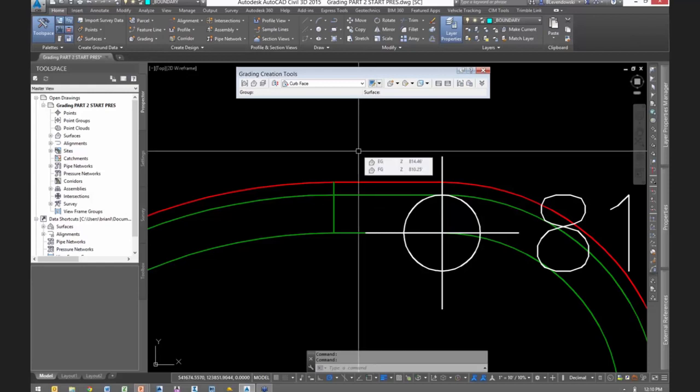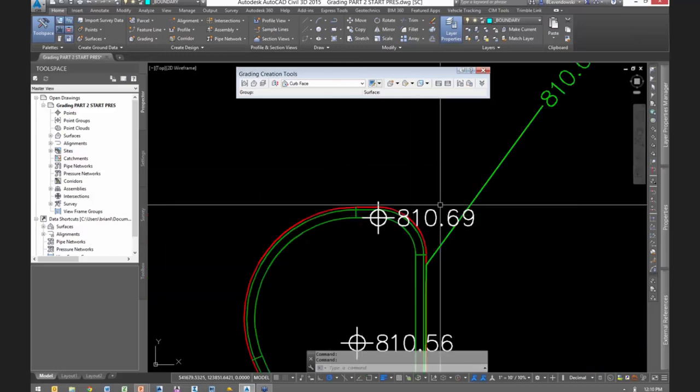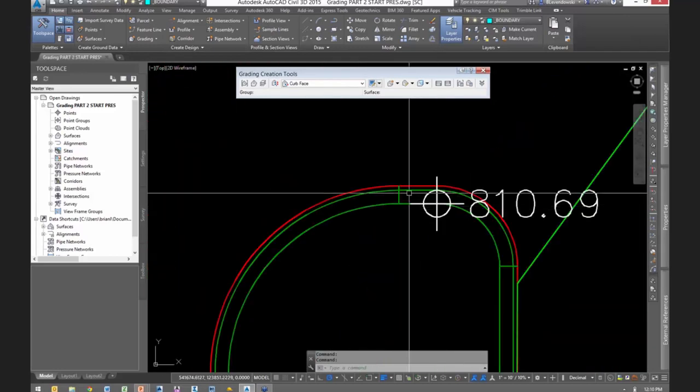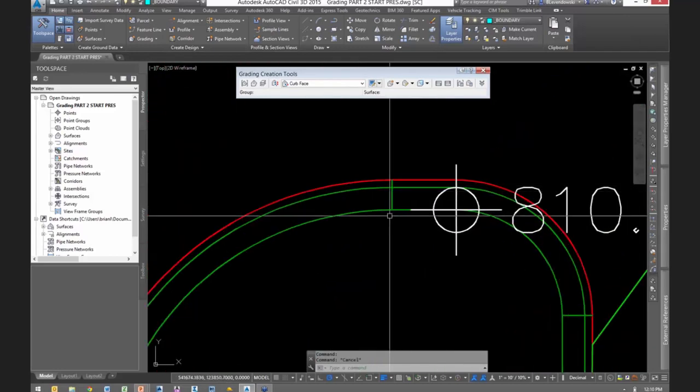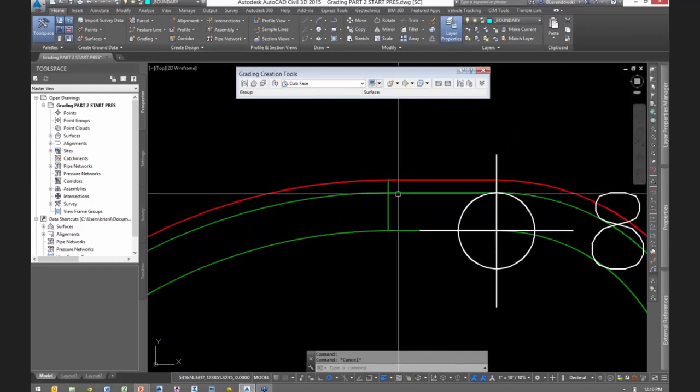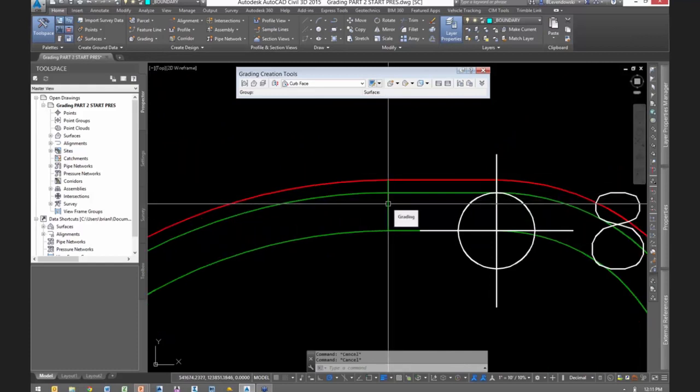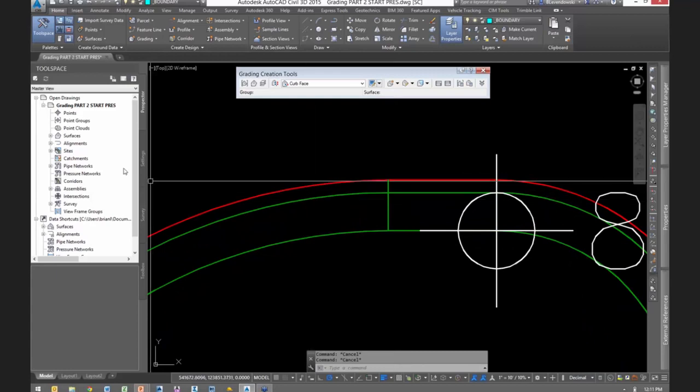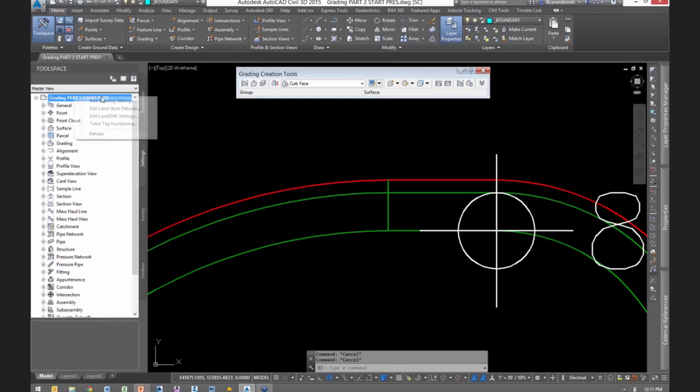There was another item mentioned about final sheet creation and plotting and all that. I don't want to get into that in a ton of detail here. There's a lot involved with that. A lot of it comes down to the styles. For example, we wouldn't want to be printing this line. And so I've used object layers with wildcards to be able to turn those lines off fairly quickly.